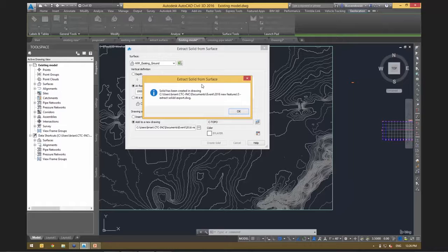Another thing to mention, migration. A lot of folks believe you should migrate only 1 year at a time. So in your cases, you're going from 14 to 16. I could probably do it in front of you right now and we'd have no problem going from 14 to 16, but there are people recommending only 1 year at a time. So if you have 15, I'd say go to 15 and save it, and then go to 16 and save it there.